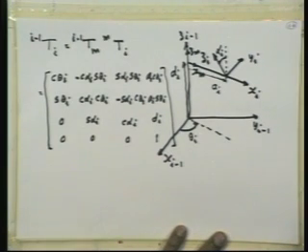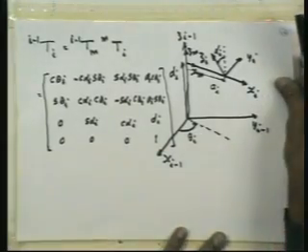What we did was consider the 6 revolute manipulator, set up the reference frames on each link, define the linkage parameters and the joint variables, and then we saw what the general form of the transformation matrix is from one link to the previous link. This is a 4x4 homogeneous transformation matrix, and using them we can very easily solve the forward kinematics problem,